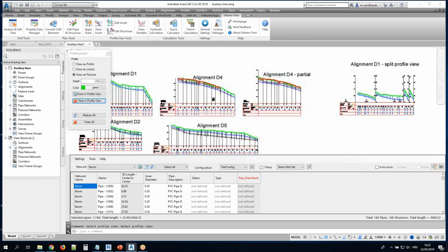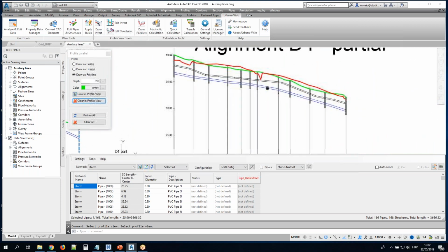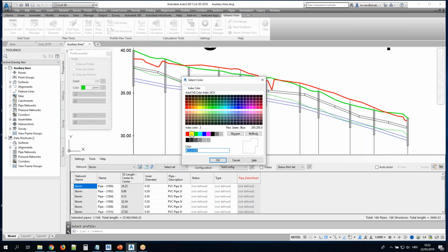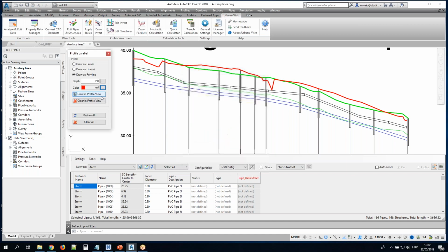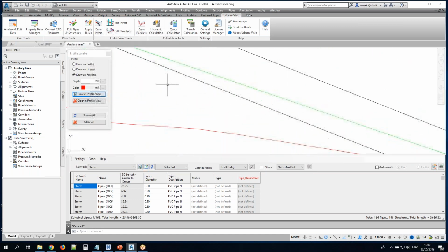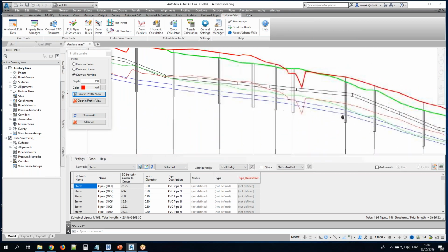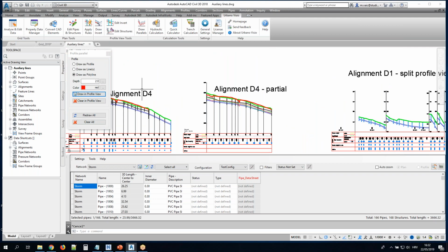If you have a more complex situation with two terrains, then, for example, you just need to select the appropriate terrain. Okay, now I'm getting the green one, and for example, now I can switch the color to red, and again go to the same profile but to a different terrain line, and now I get two terrain lines, each on a 2-meter offset to the terrain.